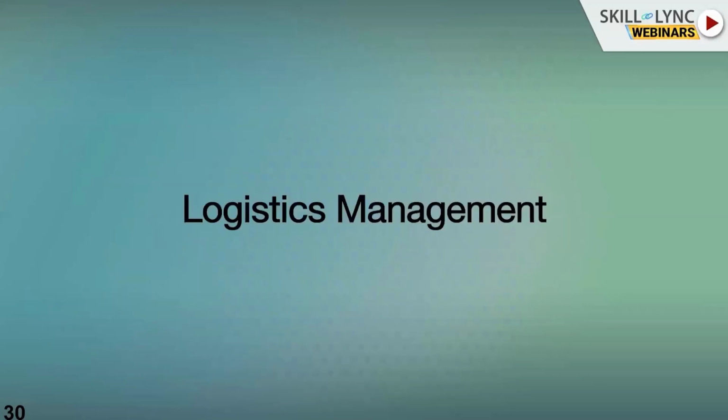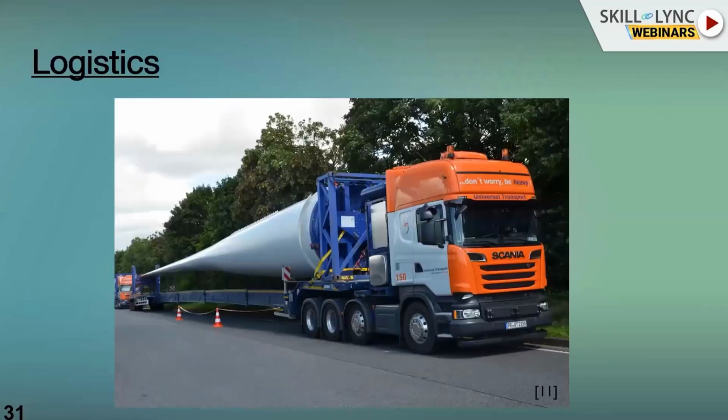And logistics. Logistics involves very huge components. Because of the huge components, internal road transport is also critical, as is sea transport. Many components, mainly blades, get damaged during road transport, shipping, and shipping to the site. Some sites are offshore, and then different transporting methods are required. So logistics and transporting are the challenging part for wind turbines because of the component size.